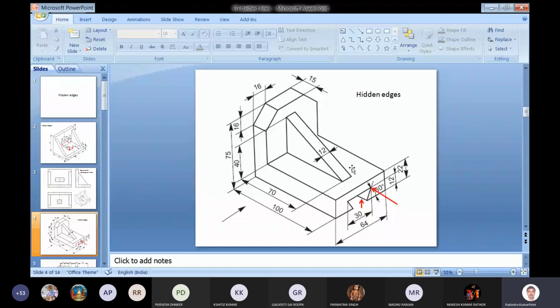These can be drawn in some view. Which view will they be drawn in? They will be drawn in the top view, because if we see from the top, we will not be able to see these edges. So they will be drawn as dashed lines in the top view. And in the front view, you can see all the edges. Here one edge is hidden, but corresponding to that, here we have continuous edges. So the priority is given to the continuous edges. The continuous edges are drawn, so we can ignore this edge.